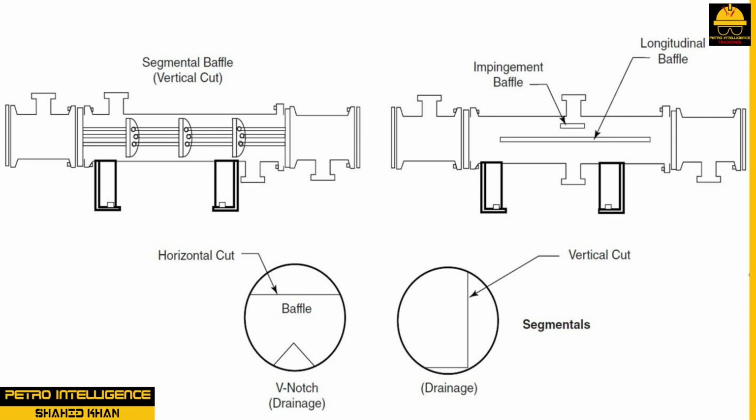Single-pass exchangers do not need a baffle in the inlet or return head. Multi-pass exchangers requiring 2 passes will have a single baffle in the inlet channel head. A variety of baffle arrangements are available. Cost goes up with each pass. Additional passes are often needed to provide adequate fluid velocities to prevent fouling, internal buildup of material, and to control heat transfer. Segmental baffles, as shown in picture, are often used in horizontal shell and tube heat exchangers.